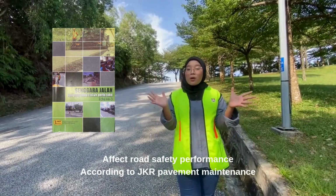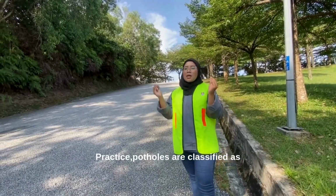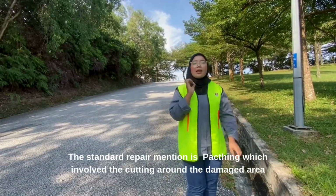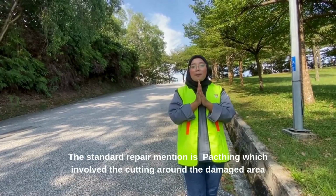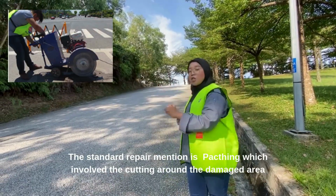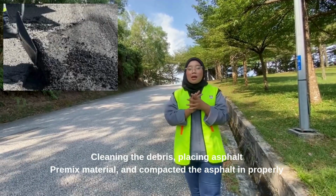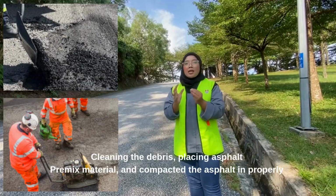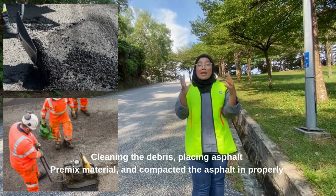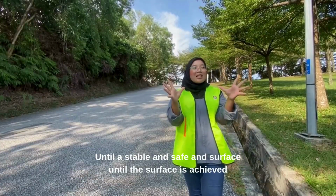According to JKR pavement maintenance practice, potholes are classified as a critical defect that requires urgent repair. The standard repair method is patching, which involves cutting around the damaged area, cleaning the debris, placing the asphalt premix material, and compacting it properly until a stable and safe surface is achieved.